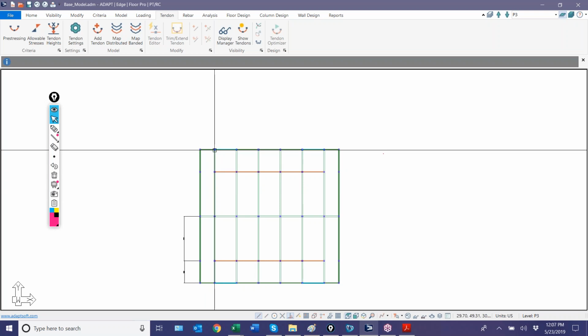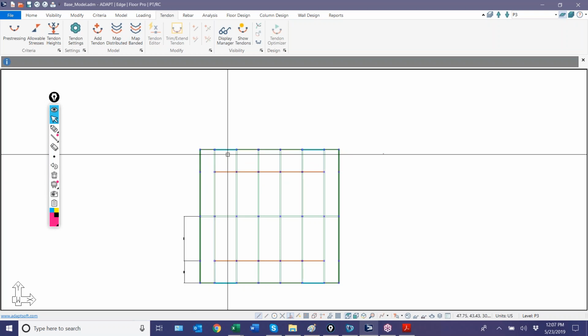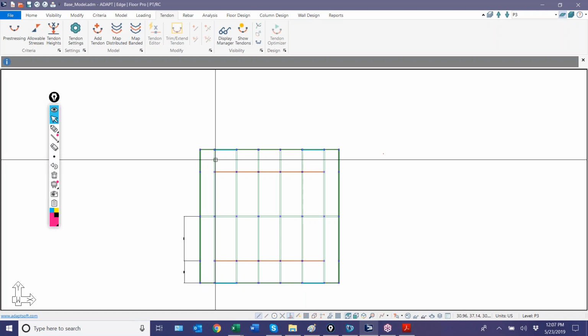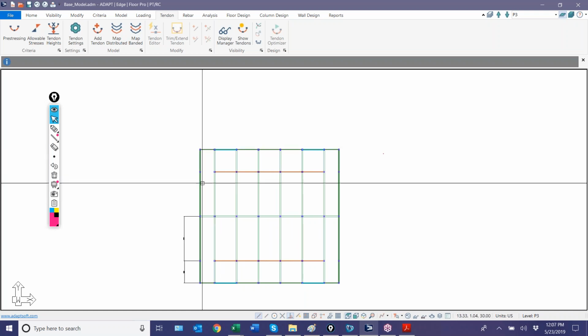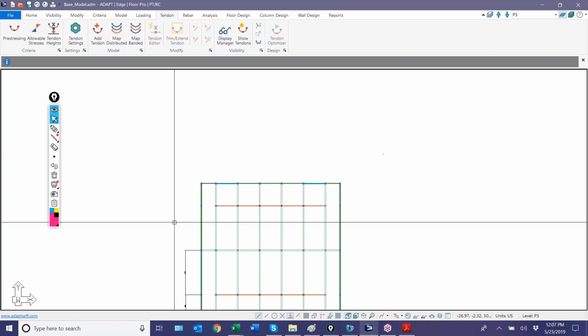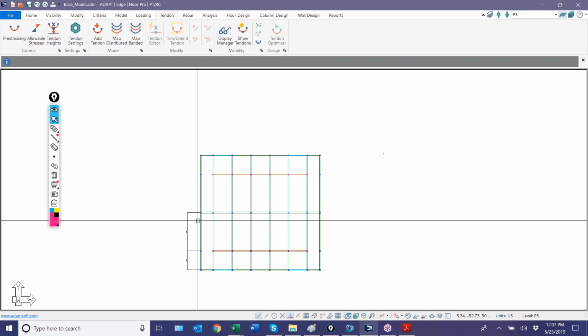And I realize that, for example, this beam doesn't have quite the same tributary as these beams here, but we're gonna just apply this to all beams except for the perimeter, and we'll actually just cut that force in half. So we have 456. And we have to make a decision as to what the effective force is going to be.